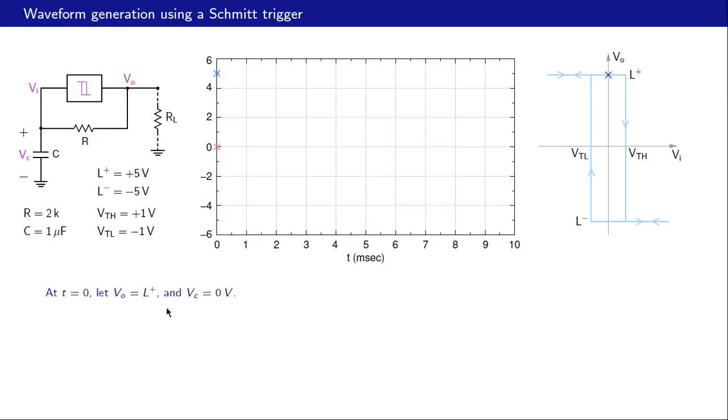Alright, so let us show this charging process. That is how the capacitor will charge. Since the time constant is 2 milliseconds, in about 5 time constants, that is 10 milliseconds, it would charge towards 5 volts, and the charging process would be almost completed. Now it doesn't quite reach there, and let us see why.